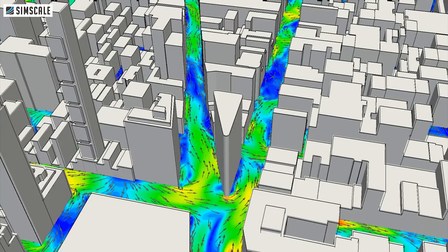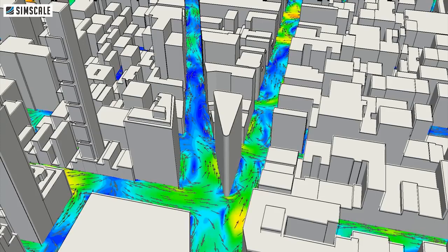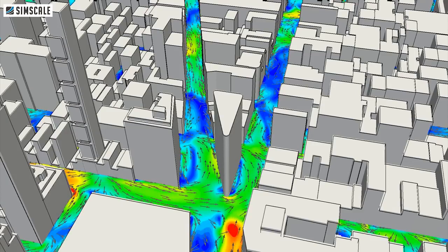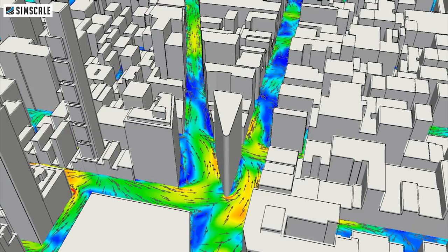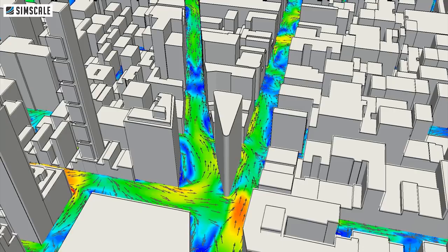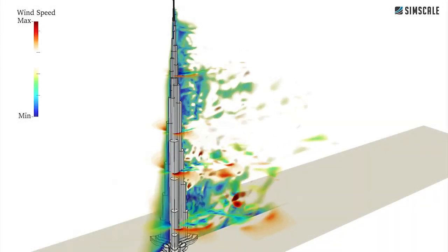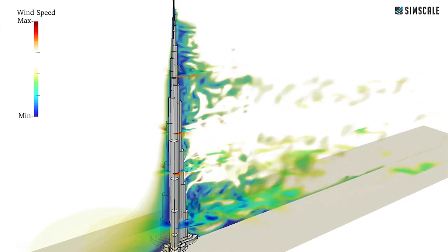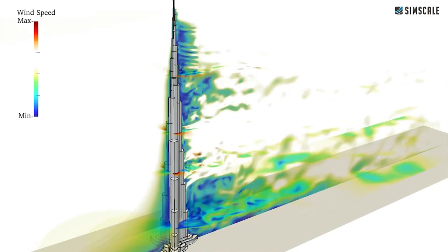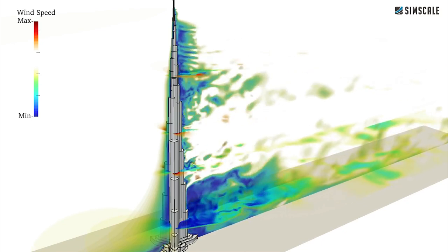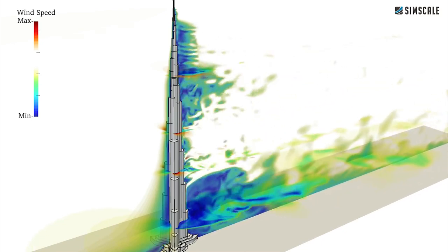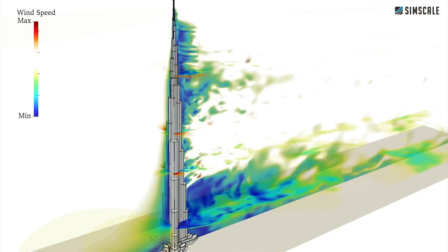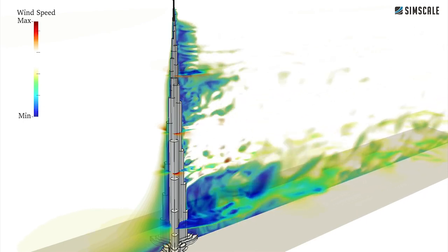In these conditions, the wind gusts reach the front leading edge cone shape of the building that creates accelerated flow and vortices on the Broadway and especially Fifth Avenue side. Wind loads on buildings. We can see the main effects of the structure optimization in this animation that shows the flow physics at 3 different cross sections along the height. Close to the base height level, the area is the largest, and so is the wake behind the structure. But the corner softening helps to avoid strong vortexes.